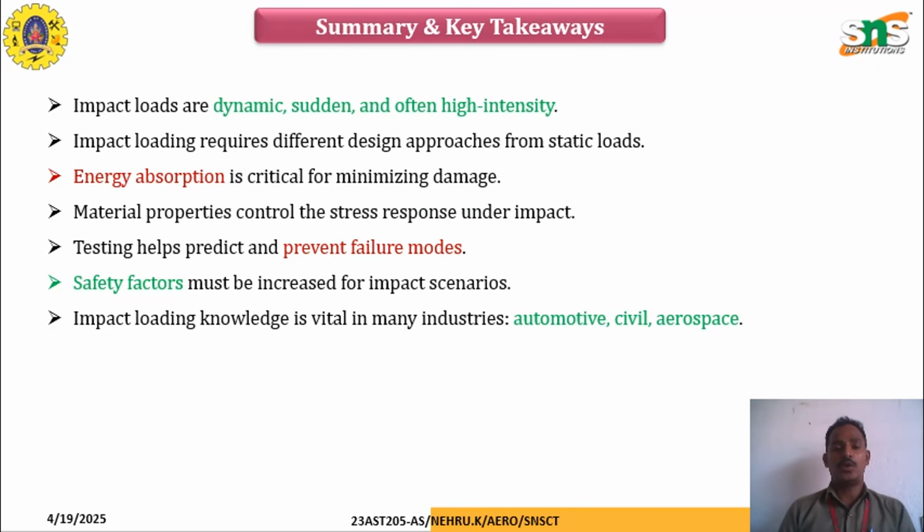So here we conclude and summarize today's class. Impact loads are dynamic, sudden, and often of higher intensity. So impact loads require a different design approach from static loads. Energy absorption is critical for minimizing damage. Material property is another factor to ensure how much failure prevention happens during various modes of failure. A safety factor must be introduced for impact scenarios by using energy-absorbing material. Impact loading is relevant in many industries like the automotive, civil, and aerospace industries, and so on.